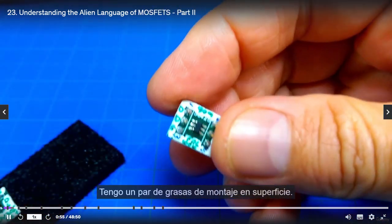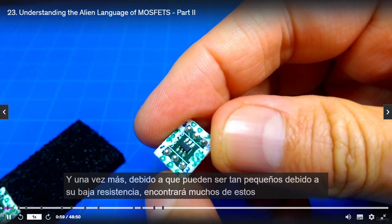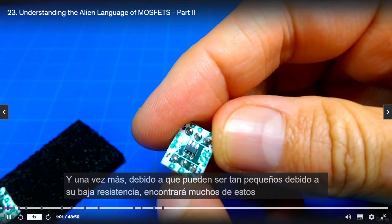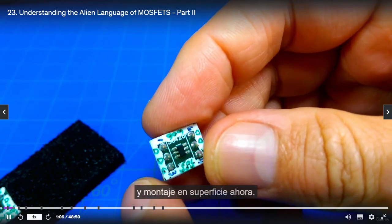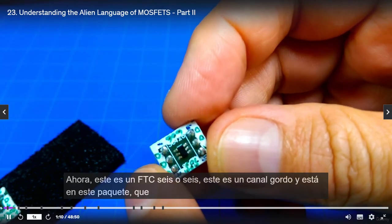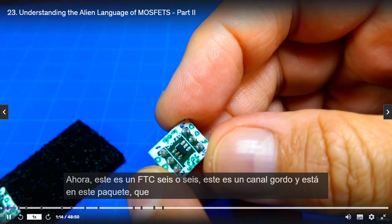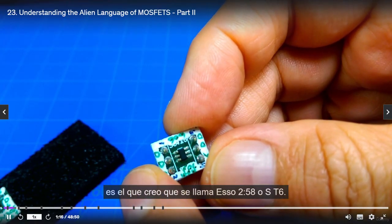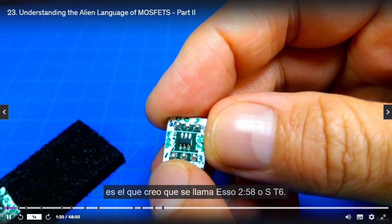Here I have a couple of surface mount FETs. Because they can be so small, thanks to their low on resistance, you're going to find a lot of these in surface mount now. This is an FDC606. This is a P-channel FET, and it's in this package, which I believe is called a SOT23 or an SOT6.